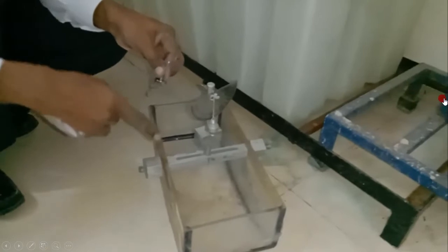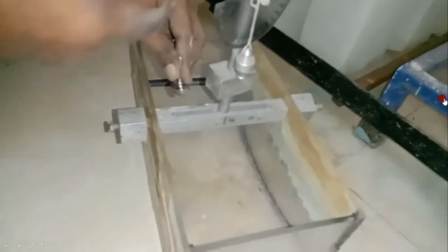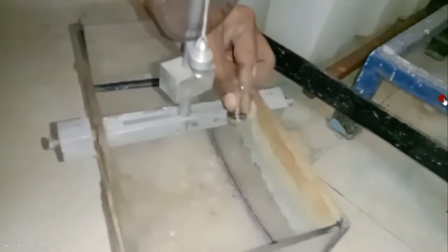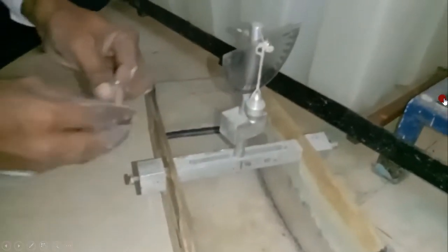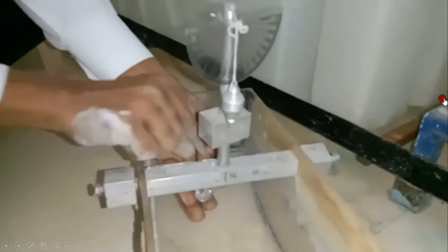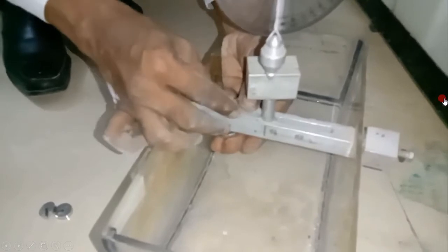What we will do, we will use the left hand side of the ship. We can perform this experiment by applying weight on the left side first and taking different readings. After that we can take this weight to the right side and take different readings. So now I will attach this on the left side. For attachment, here is the procedure that we follow. This is a hanger weight. Here is a screw arrangement. Now we have added only one weight, means 16 gram, and we have put that at a 10 mm distance. Now we will put this ship here.